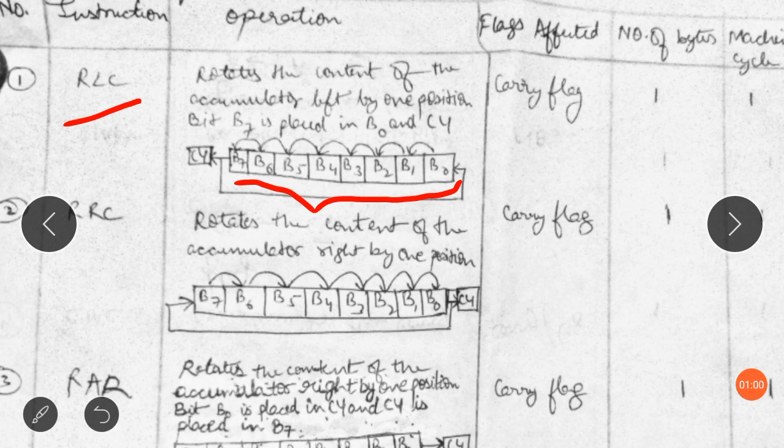Now after execution of the instruction, each bit of the accumulator will rotate towards the left by one position. That is, B0 will come to B1, B1 will come to B2, B2 will come to B3, and in this way the last bit B7 will go to the carry flag, as well as to B0. Now let's take an example. Let us suppose the content of the accumulator initially was